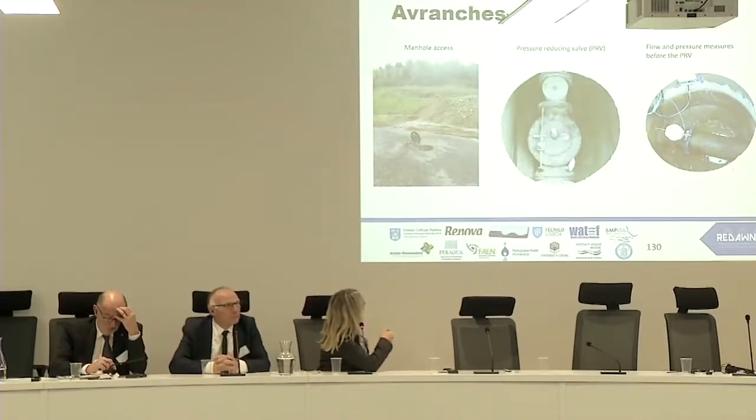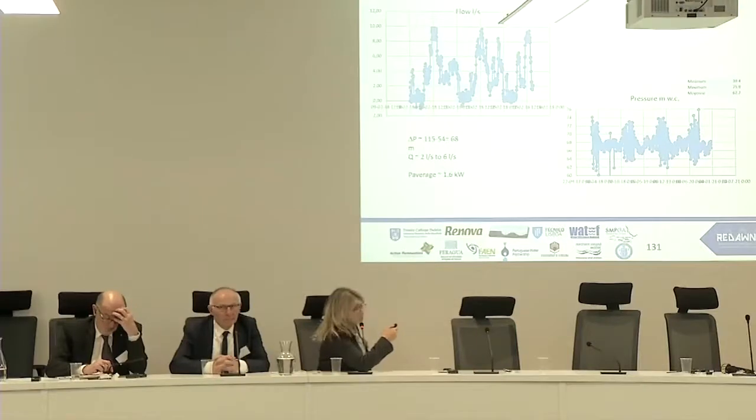Yesterday you saw the manhole where there is a PRV, and upstream we are making some measurements, some registrations of pressure and flow in our system, in order to understand how the flow varies along the day, and the pressure associated to this flow, okay? And we can choose in the best way the micro solution.